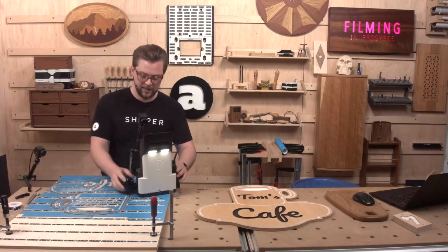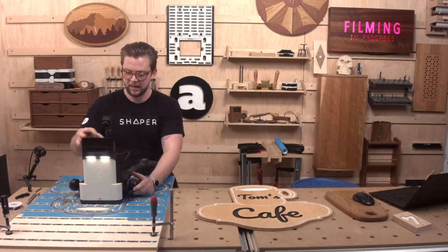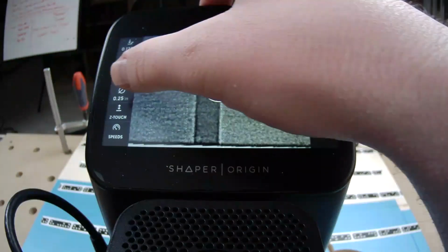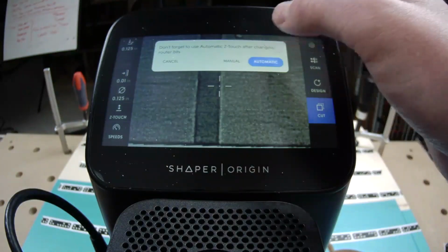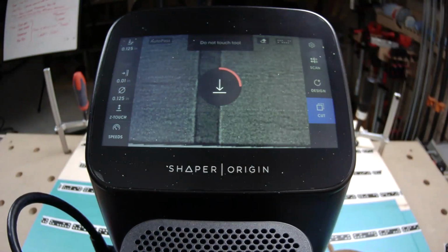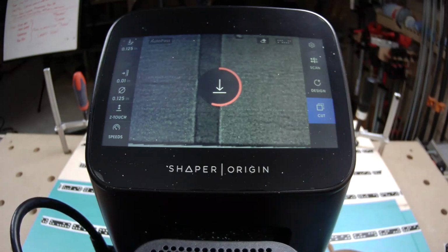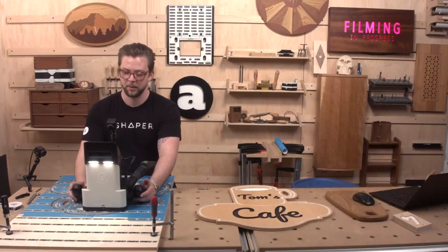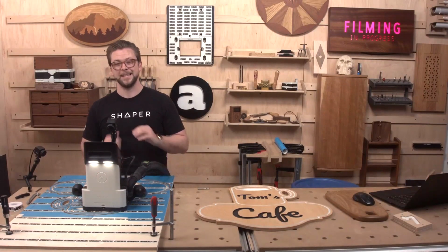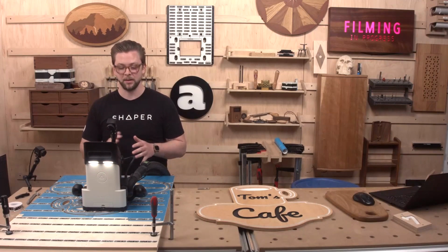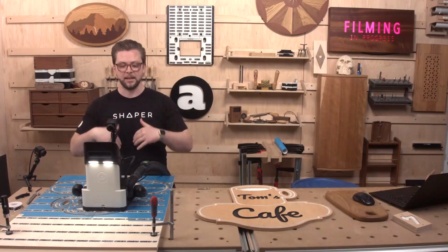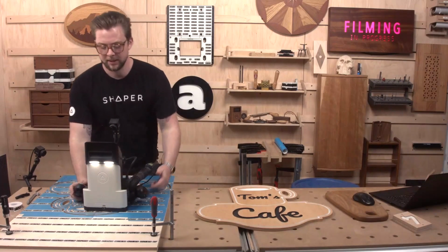Okay. 1/8 inch down cutting bit back in. You probably saw that I wasn't able to get all the way in some of those areas with the 1/4 inch bit. So I am going to be making a fresh cut with a down cutting bit. I'm just going to be really cautious not to hang out in those areas, because again, we're just pushing all that debris into the cut. So I'll be nice and steady going through those.